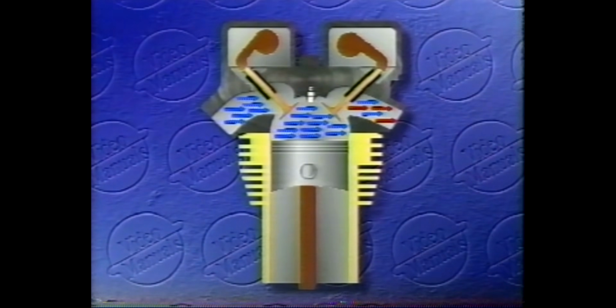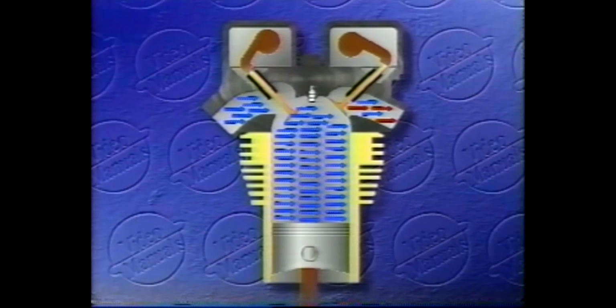For example, at higher RPMs and with a tuned exhaust system, a strong vacuum is set up by the exhaust gases as they escape through the slightly open exhaust valve. This vacuum helps to suck in fresh fuel-air mixture, just as the inlet valve starts to open. Quickly filling the cylinder with new fuel-air mixture dramatically improves the volumetric efficiency and the flow through our heads, giving us more power and performance.